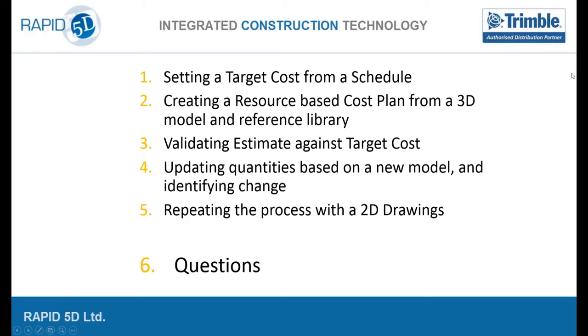Okay, so first one's come in. Someone spotted that I used an NRM1 structure in my cost plan there and asked if they have to use an NRM1 cost plan. You don't. You can use any structure you like, really. We've worked with customers who've used SMM7 and even SESM or RMM. And the reason we use NRM1 is because it's most suited to the BIM way of working, and we can really gain benefits in the long term for benchmarking our pricing data. So that's why we use it, but it's completely possible to use any structure you like.